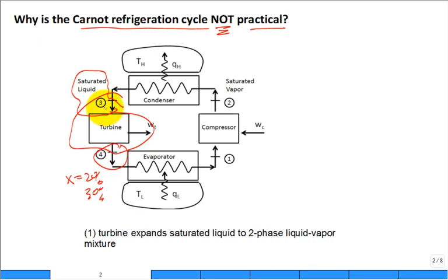Okay, the next one would be, we learned about pumps and compressors. We learned about happy pumps and sad pumps, and we learned about happy compressors and sad compressors. For a happy pump, what do you feed it? Liquid. And you can get it up to saturated liquid, but don't get it past that where it's got a liquid vapor mixture. The best you can do would be feeding it saturated liquid. Oh, subcooled liquid or compressed liquid, it's even happier, but at the limit it would be saturated liquid.